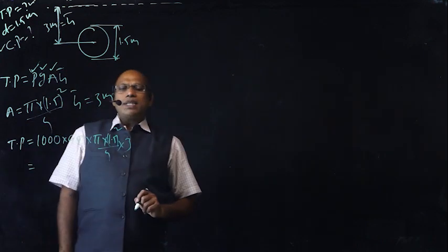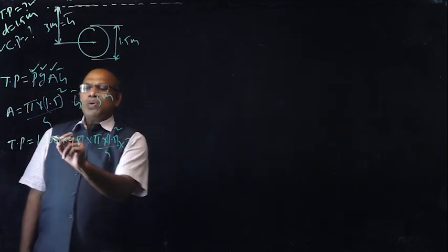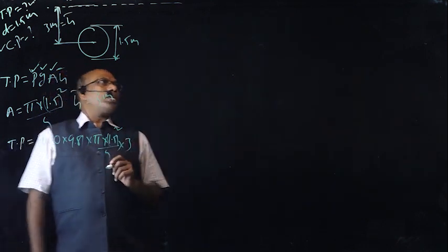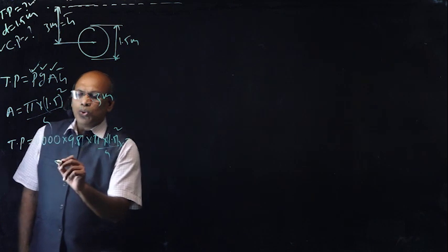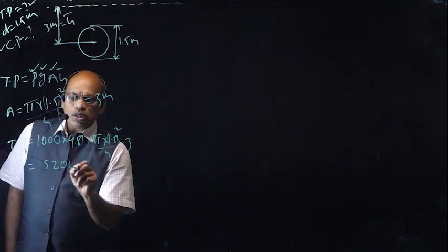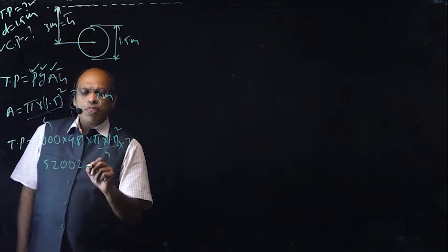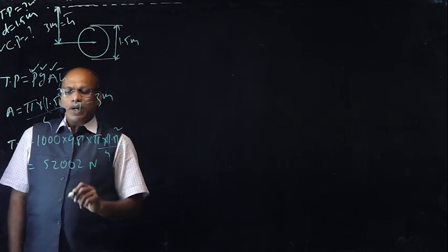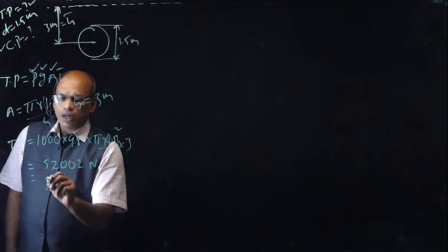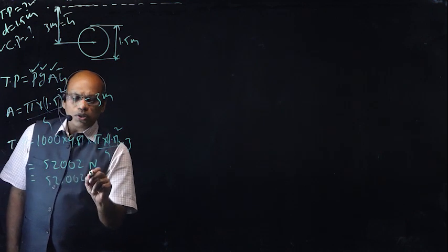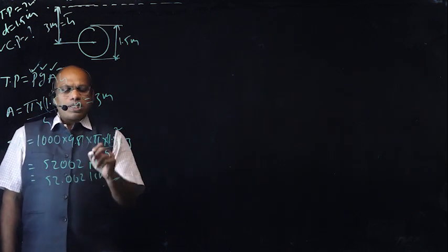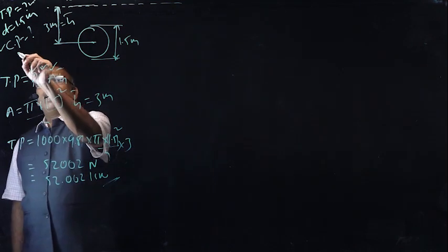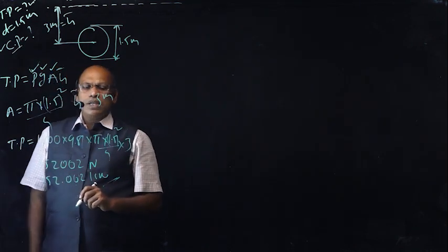Therefore, from this equation, finally total pressure or pressure force is equal to 52002 newtons, or 52.002 kilonewtons. This is the pressure force or total pressure. Now we are going to determine the center of pressure.